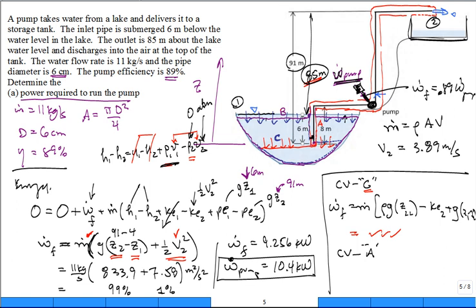The last one, control volume A, which you said I'm just going to cut it real close and come around the pipe, the inlet to the pipe right in here. The problem with that control volume is, what's the pressure at the inlet to the pipe? Is the pressure at the inlet to the pipe hydrostatic below? Is it 6 meters of hydrostatic head? Is it rho GH, which H is 6 meters? The answer is no. Otherwise, it's not going to flow to the inlet of the pipe.